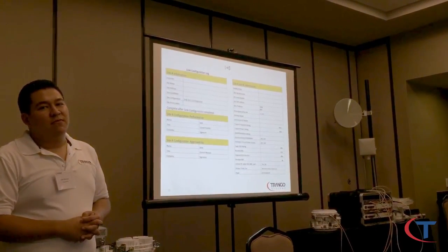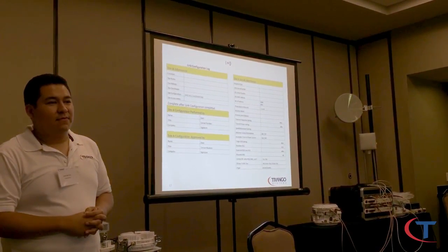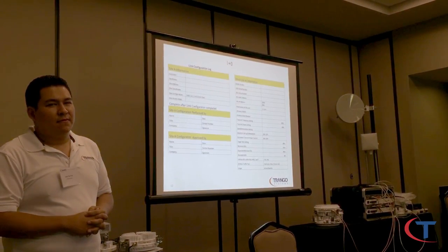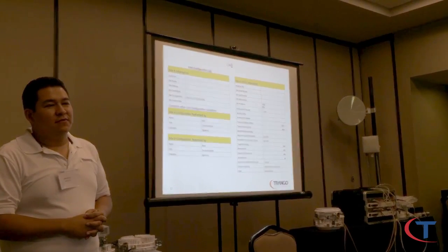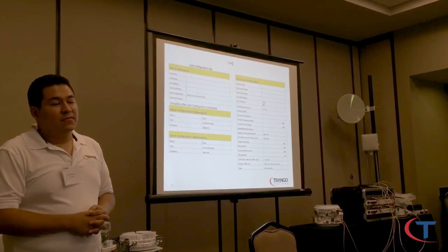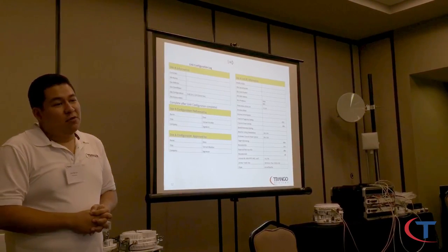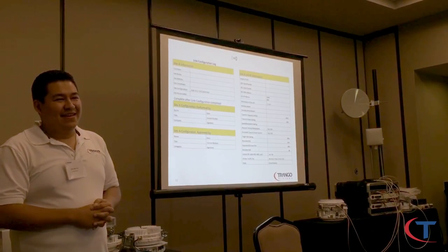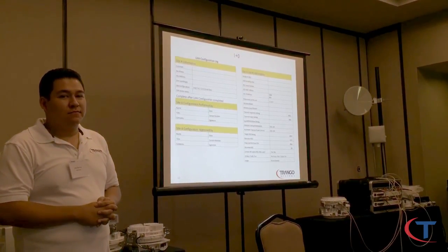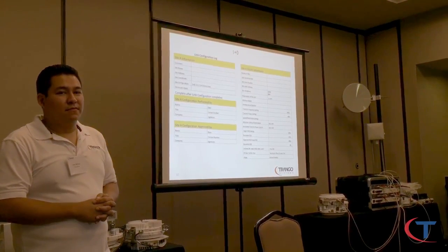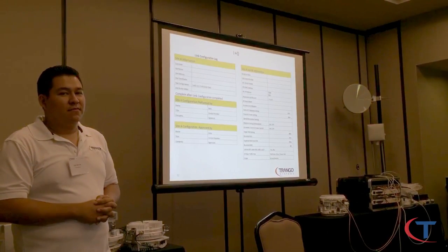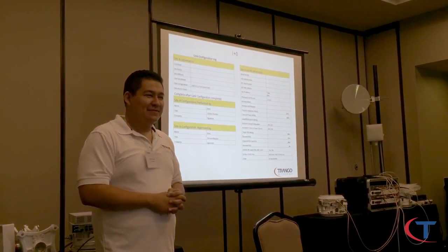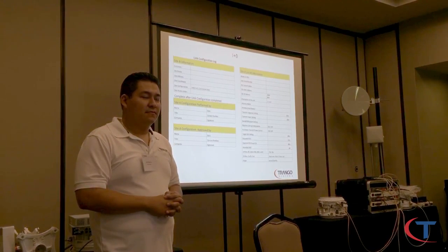You need a dual polarity antenna with dual waveguide coming out to 2 separate standard combiners for a 4+0 or 3+0. Oh, okay. So it can be done with a single antenna. Yeah, I have some pictures of that. It's becoming more common. A little bit of plumbing involved with the waveguides, that's all. I imagine, because there is no combiner which puts 4 radios, that would be kind of a monster contraption. It's too heavy for the antenna. So you have to do it with waveguide and then 2 separate combiners and a dual pole antenna with dual waveguide inputs.